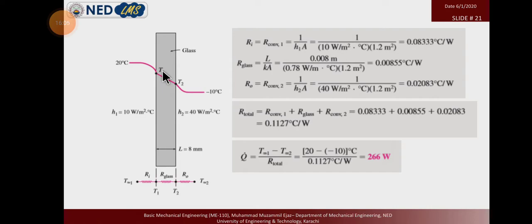It's a very simple numerical problem you can apply in your daily experience. Just get a digital thermometer or temperature gun, calculate the temperature of the room inside, and with the same thermometer calculate the temperature outside, and take the difference of temperature. If you know the wall material and its thermal conductivity, you can easily calculate the heat transfer. Now the second thing we need to find out is the temperature T1. By this formulation we can also get unknown values like T1.